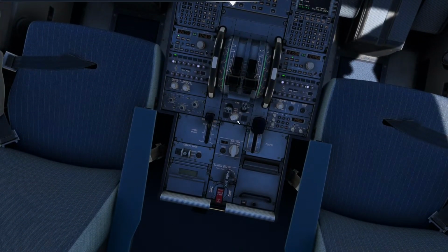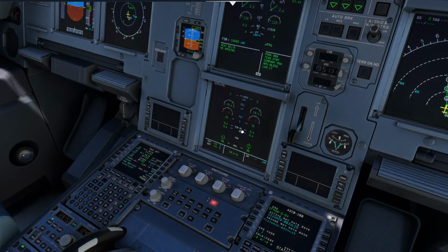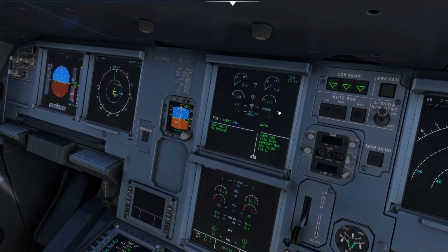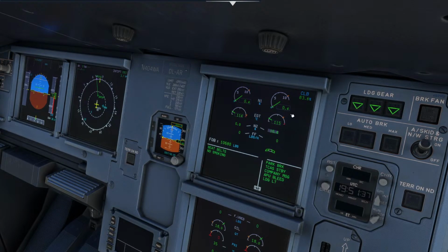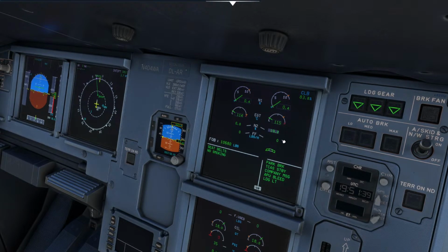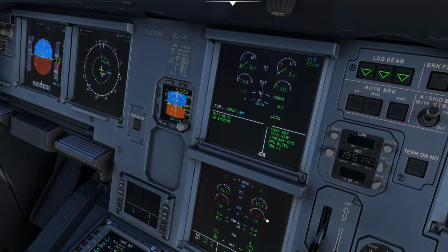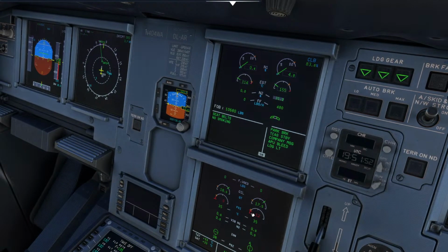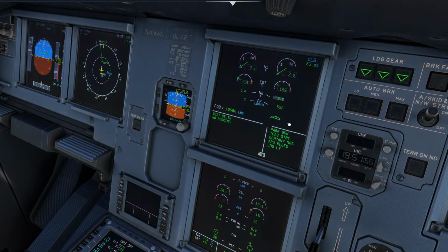All right, and then we're going to go to ignition start. Now come over here, we'll go to the engine page. If you notice, I've got N2 rising, right? Bleed air is now getting pushed into there, and it's all going to do this by itself. If we have a hot start, then we could just close the ignition switch. So now if you notice, there's EGT, and there's oil pressure coming up on engine 2. Fuel flow's coming up. It's all automatic. It's just like the real airplane.